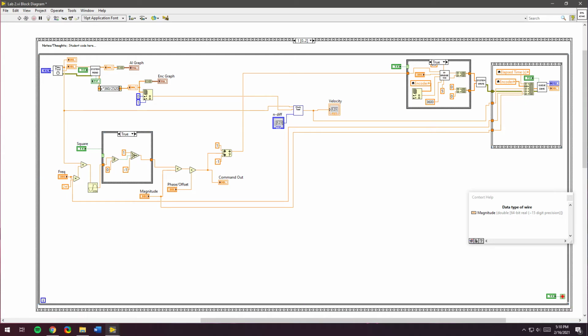And then finally, we want the controller command signal, so that's what we're actually sending to the H bridge. I'm going to put the coerced, but I'm going to need one more box. So again, just hover over the bottom and drag it down to get an additional save spot. And then just connect a wire. And so we should be good. Again, you can see on the left, we have a solid white arrow, so that means nothing's broken.